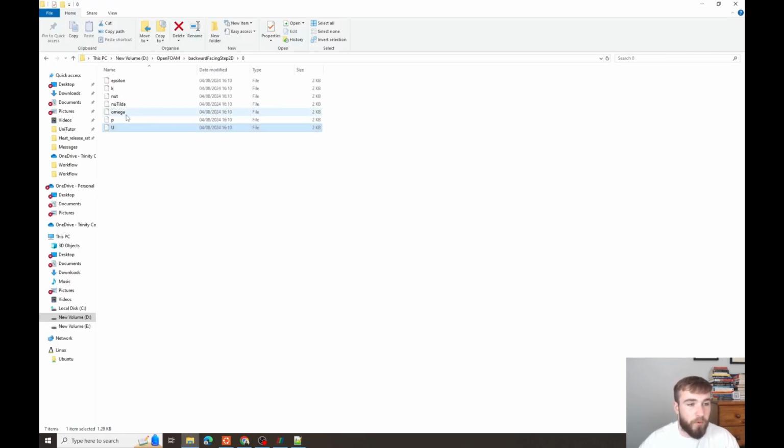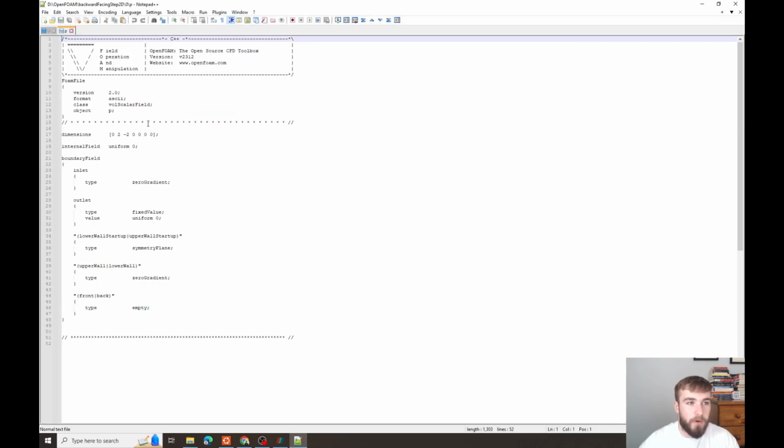Next, we'll talk about the pressure boundary condition, because this can be quite important because pressure and velocity are obviously coupled. So an important thing to note here when you're running your OpenFOAM simulations is it's not like ANSYS, where ANSYS wouldn't let you apply, let's say, a fixed pressure and fixed velocity at the inlet, because that doesn't make sense.